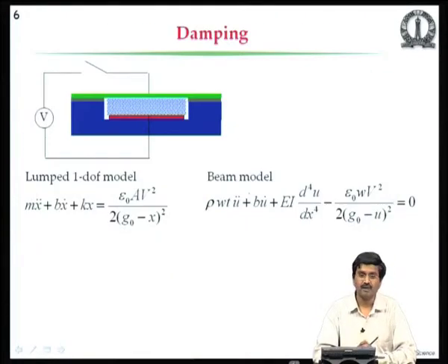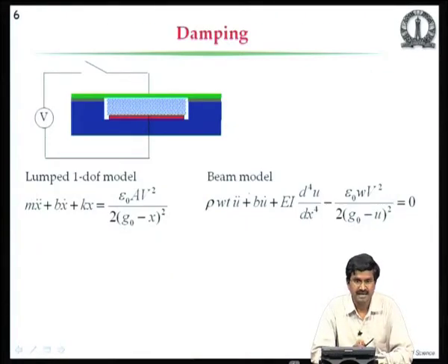Okay. Now, when we talk about damping, we have to deal with the fluids, because microsystems necessarily involve fluids unless it is vacuum packaged. If I take an accelerometer and vacuum package it, there is no really fluidic effect there, because only the solid moves, but even then there is nothing like a perfect vacuum packaging, there is nothing like a perfect vacuum.